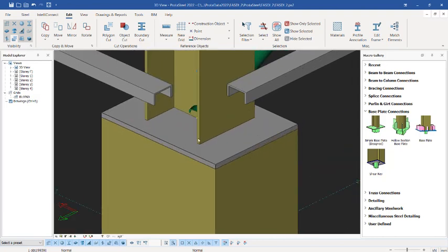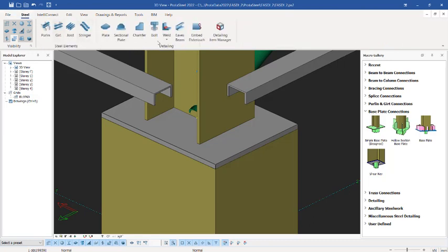Okay, this time around we want to be adding holes on this, followed by the anchor bolts, so that we can actually bolt this successfully. For us to do that, we go to the steel sections. In these steel sections, you see bolt here, this one. Click on it once. Once you click on it, you select the plate that you want to place the bolt on, after which you right click and then you pick the first point right there, come over here and put the second point. Okay, so it will show you this.